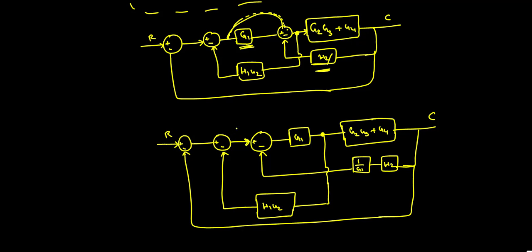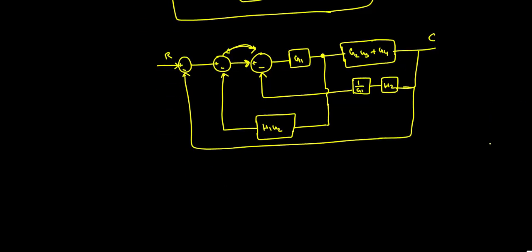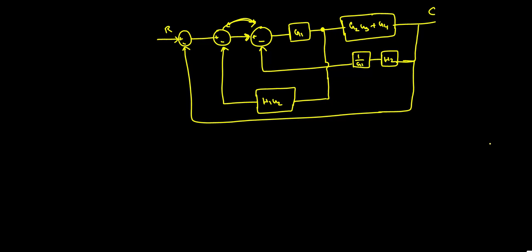If you try to interchange the summation, then if this summation is coming here and this summation is coming here, this will form one path and this will form another path, G by 1 plus GH form. So we have to slightly interchange the summation path, and then let us see what is happening. If I bring this to here, what is the effect that is coming?